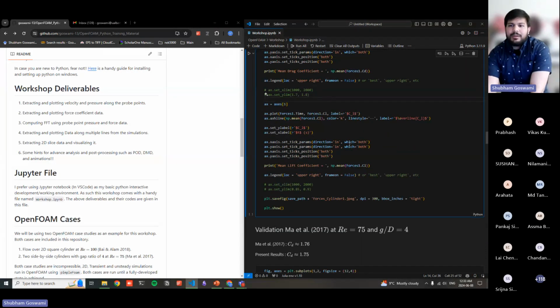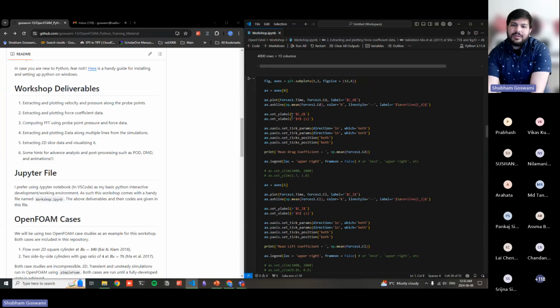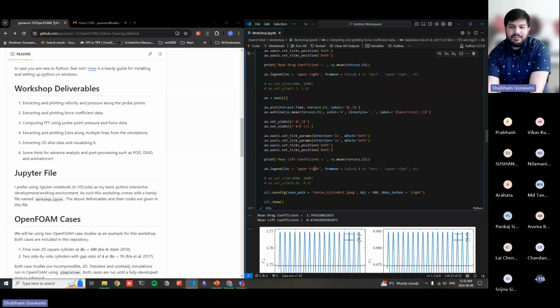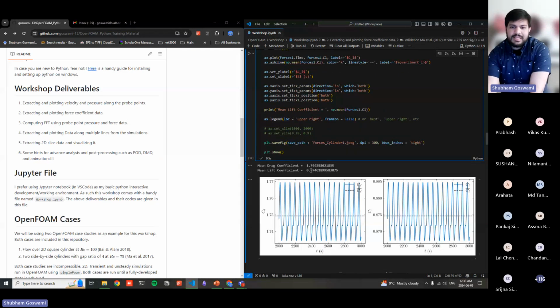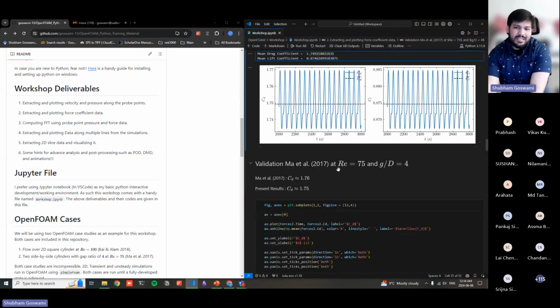And then you can just simply plot it using common plotting routines. Here I've passed on a couple of variables, basically plotting my mean force, like mean drag and mean lift for those cylinders. And I get a value of my mean variable there. And I also see the trend of the unsteady drag force that's acting on the cylinders there. So once I have that information, it's really easy to validate it